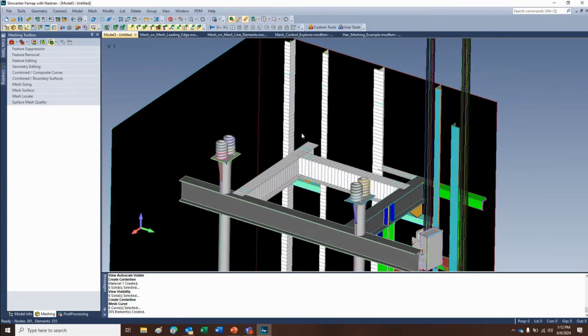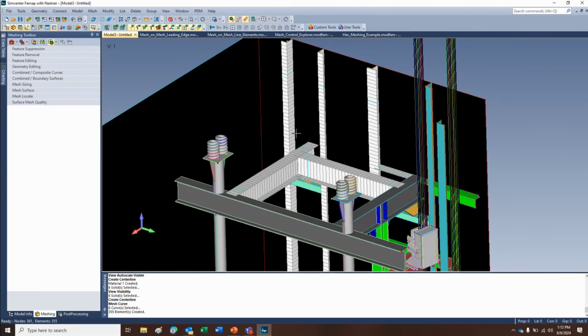And they were all turned on, basically your thicknesses. It's not trying to make a plate mesh. It's making general section beam meshes. But it also does take into account all shear center offsets, everything like that you need to get it properly in the same place as where the solid was.